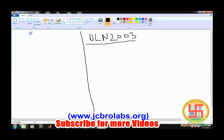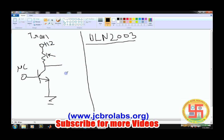So let's first understand the transistor based circuit. For the transistor based circuit, you can connect the relay like this: we have an NPN transistor in this format, and this goes to the microcontroller pin. This is 1K and this is plus 12 volt, and our relay connects here like this, and this is connected to ground. So when 0 is applied there, the relay is on, and when we apply 1 here, the relay becomes off. So with 0 it is on, with 1 it is off. It is very simple, and the transistor used here is generally the BC547 or BC548 transistor, because this series of transistors is very commonly used for switching applications.